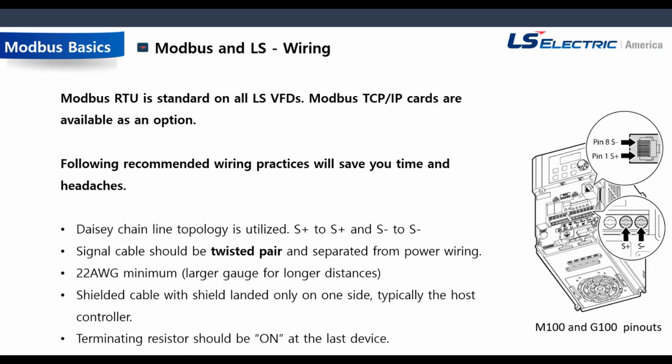Of course, we recommend following all recommended wiring practices, which I'll mention in a second. If you follow the guidelines and the proper wiring, it's going to save you a lot of time and a lot of headaches. Anybody that's worked with Modbus knows that communications either works or it doesn't, and when it doesn't work, it could be quite the headache. Even harder than that is troubleshooting noise issues where communications is randomly dropping out.